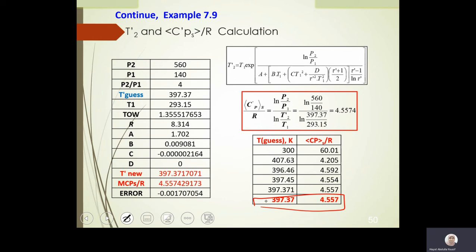Using the efficiency should allow me to get the actual work. Up to here, it was W isentropic. Here we use the efficiency to get the actual. This is the actual. By the way, this S doesn't mean isentropic, it means of the shaft. WS means work of the shaft. Isentropic is the term that refers to reversible adiabatic. So WS is equal to delta H, and I got the value. All right, so this is the actual. And according to the relationship, now remember, I will remind you, you need three main equations.